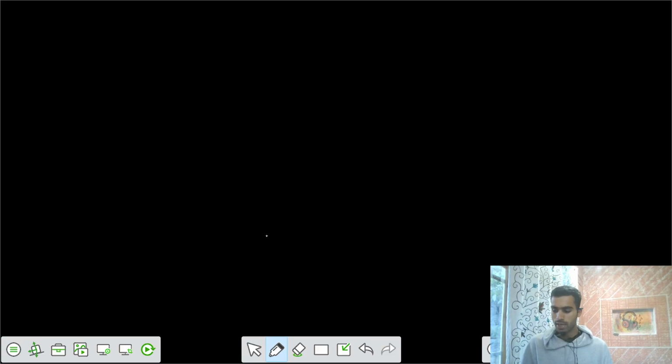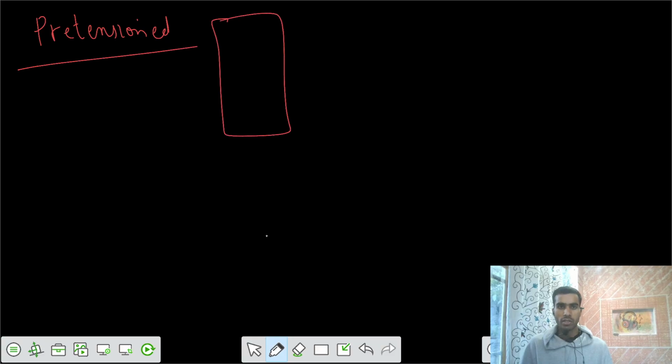Your problem is a pre-tension PSC beam of dimensions 250 by 360. We have 8 wires. Let's say there is some neutral axis, and from the soffit your wires are at 105 from the bottom, somewhere here.